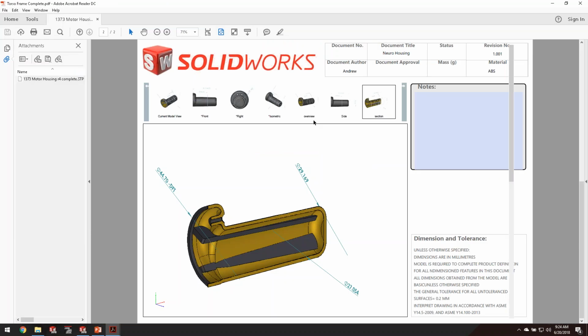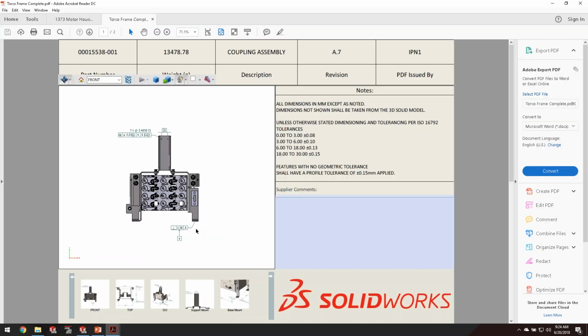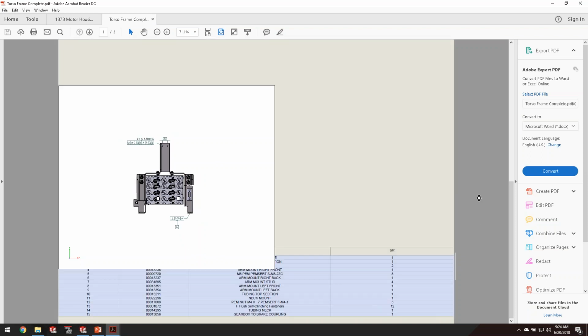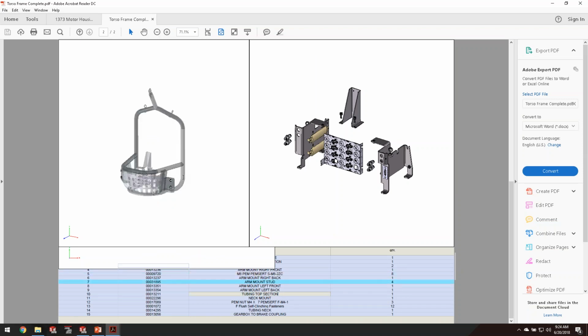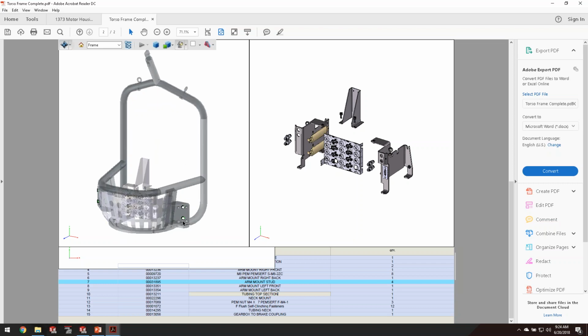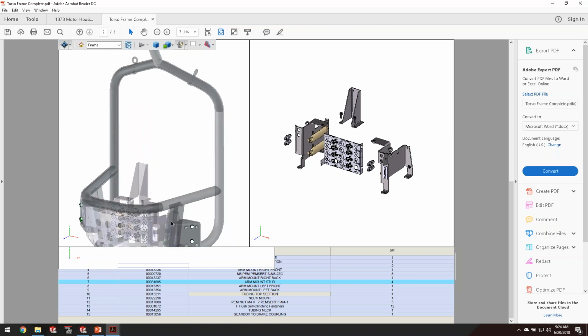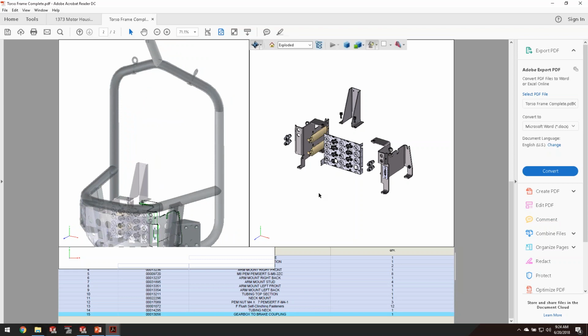So this is an assembly that I'm opening up. And depending on how you build this assembly, you could actually include things like bills of materials inside of this one. And my viewport might just be slightly off. But then I have a full bills of materials that's going to highlight and show me different components as I select on them. So as I start to dig through the system, you'll see things will shade or unshade. So there is ability to do full assemblies as well. So you can bring this in parts list and in assemblies, getting BOMs.